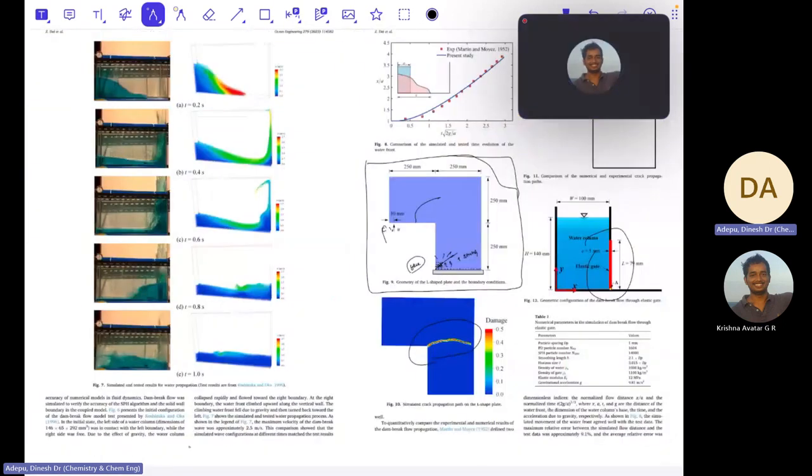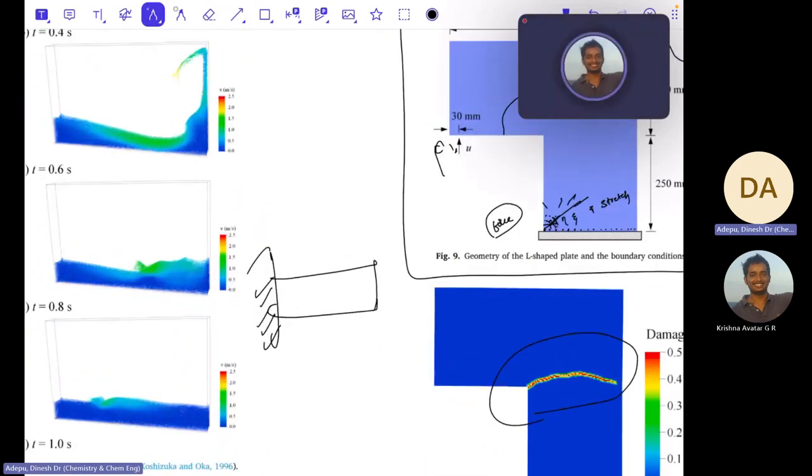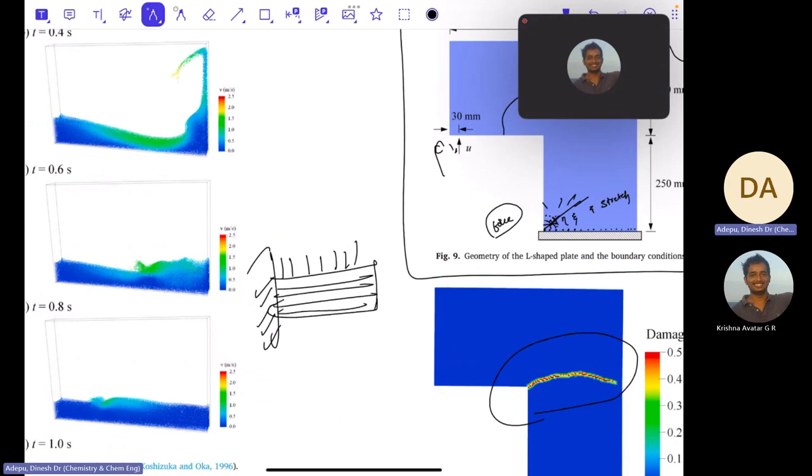Initially you can just take some simple elastic beam like this and apply some force maybe here. From the physics we know it will deform like this. We can check that with the analytical solution. And then you can check some fracture as well, to see if you have too much load, when it will fracture or where it will fracture. That could be our starting point.